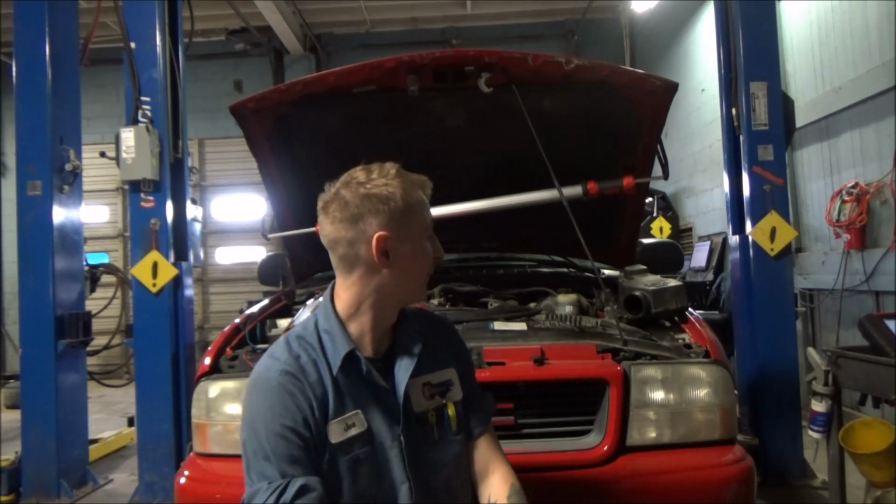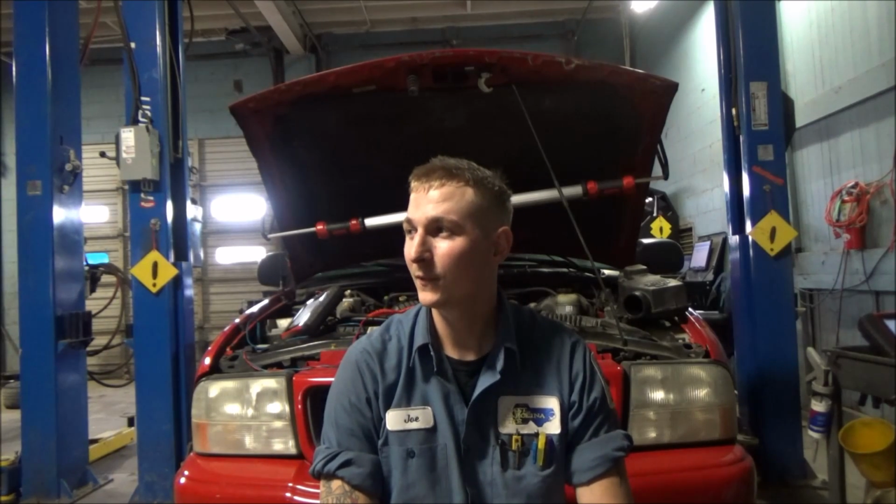But we went through a couple different methods of testing that and verifying wiring integrity to the engine computer was good. We touched on doing throttle position sensor sweep tests to catch dropouts and glitches. This one we clearly had a very clear dropout just kind of right off the initial opening of the throttle plate, so it was pretty easy to pick out on the scan tool as well as on the scope. But yeah, this one was pretty easy, guys, and we covered it pretty fast.